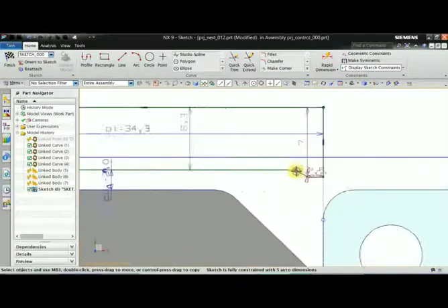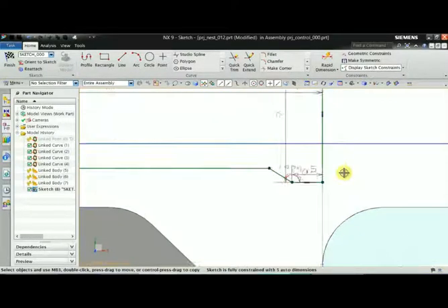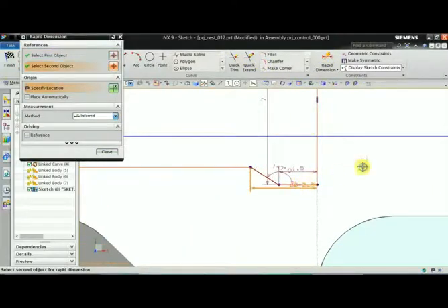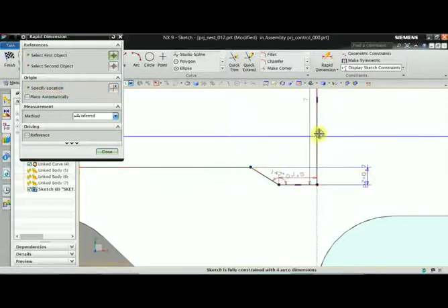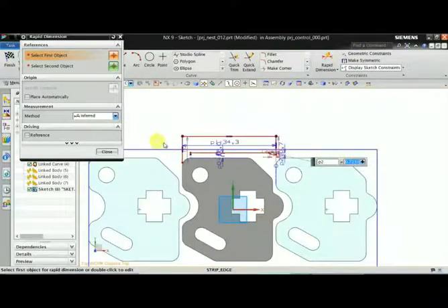You might be wondering why I'm designing an undercut like this. This profile varies from company to company, but this is one of the commonly used profiles. If we don't keep this undercut and it's just a rectangular shape, over a period of time this corner will get worn out and a thorn-like shape will be protruding out, and that will obstruct the movement of the strip.